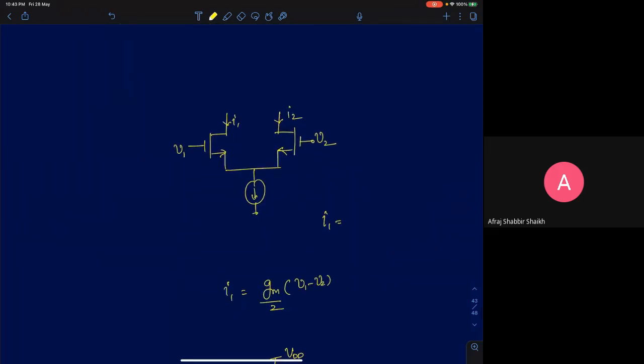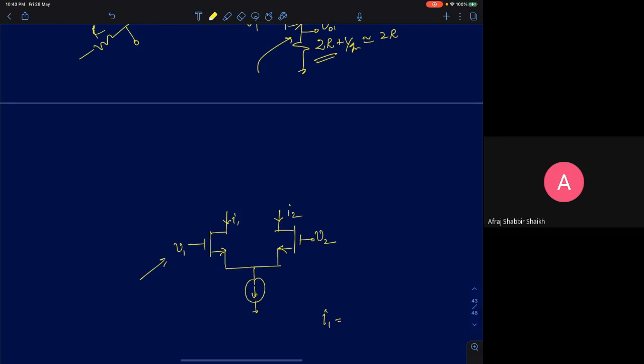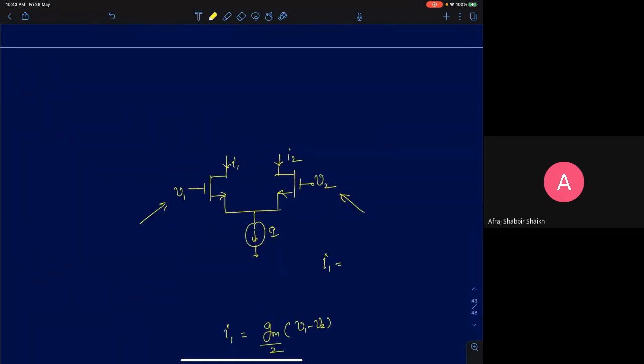Now we'll look at another interesting circuit. We'll see what this circuit does for the input voltages V1 and V2. This circuit is already familiar to all of us. This is a simple current biased differential amplifier, a constant current biased differential amplifier. If you recall from our previous lectures on current biased amplifiers, we said there is a very interesting property these amplifiers obey. As far as small signal is concerned, I is an open circuit.